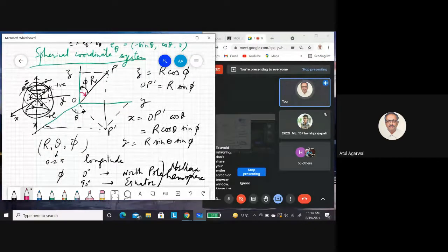In this coordinate system, as your theta changes, you get theta dot. Theta dot will give you direction k, so theta dot multiplied by unit vector k. And as your phi changes, you have phi dot. And if you look at this, what is the direction when phi changes? It will be direction e theta. So you check out how angular velocity can be represented: phi dot e theta plus theta dot in direction k. We'll see all these things, maybe not, or you just look at your books on mechanics. There is a book you have got, Mariam, it may have it. Otherwise, just Google about the spherical coordinate system. If you want to learn about it, you can learn a lot more.